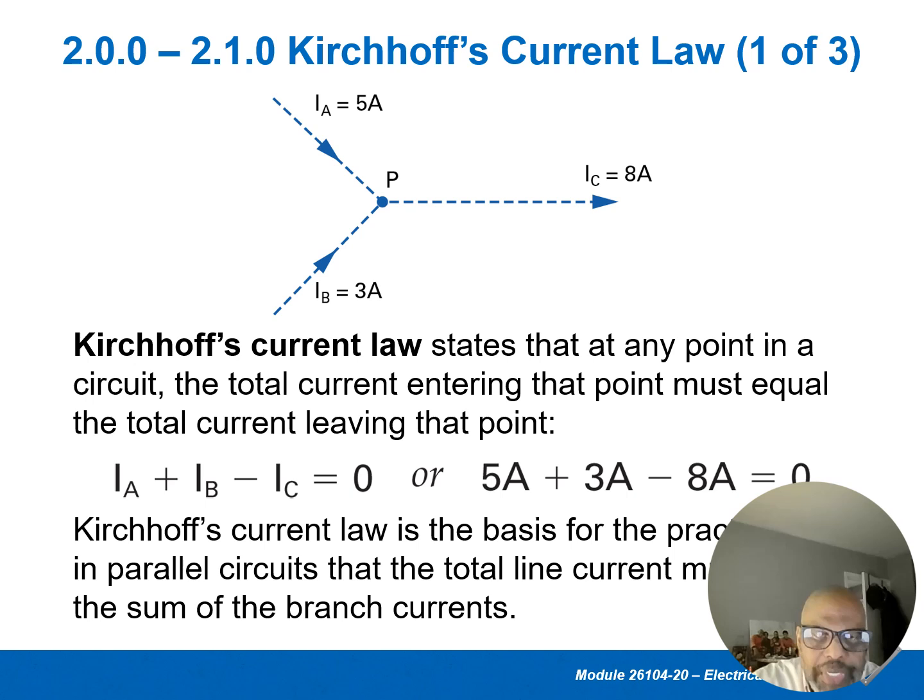Now, here's the simplest thing: things will always equal. Whatever is coming in will be the same thing leaving. And whatever the power source or current flow, it will always add up to be the same thing. So Kirchhoff's law states that at any point in a circuit, the total current entering that point must equal the total current leaving that point. So there's nothing adding or subtracting or losing.